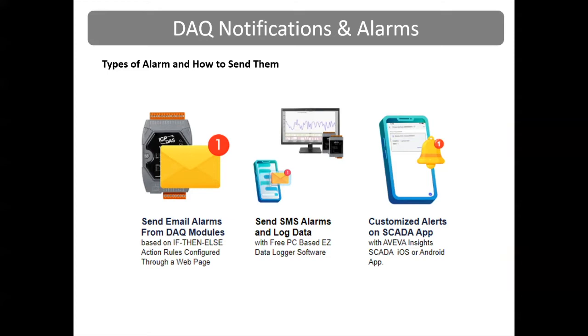Our WISE data acquisition modules and data loggers can send email alarms out, and they're set up through a web page. The WISE 7000 data acquisition modules communicate over Modbus TCP over Ethernet networks and have terminal blocks on board that you connect to sensors and equipment.